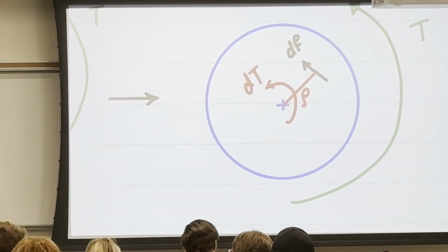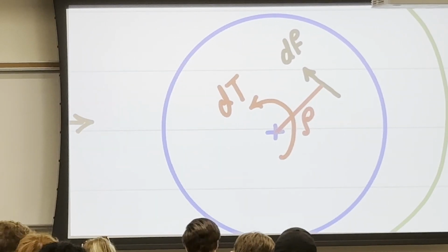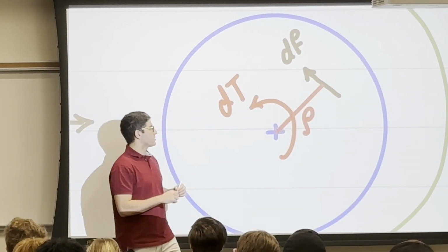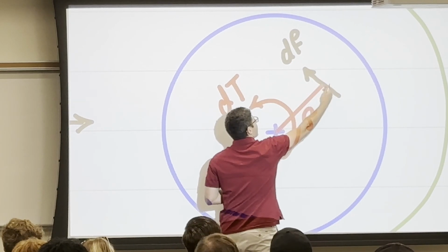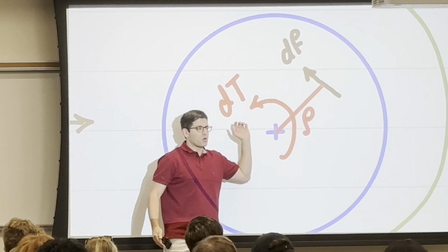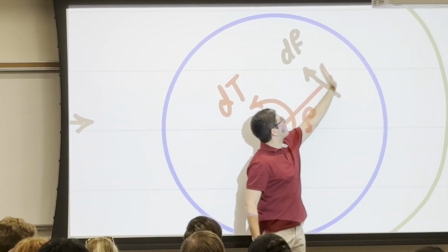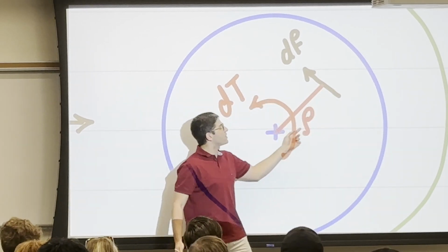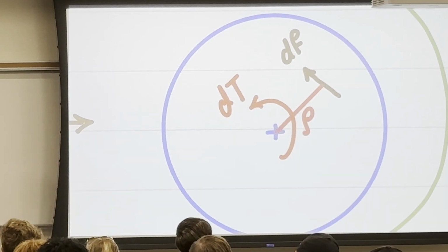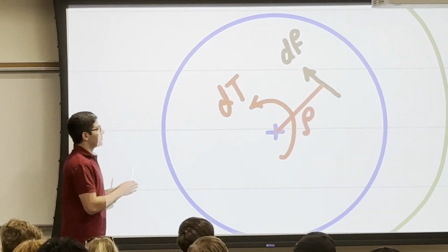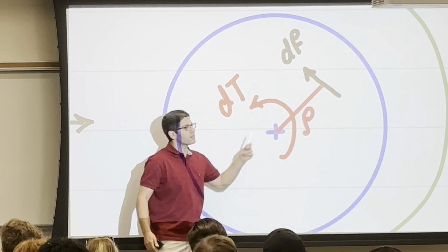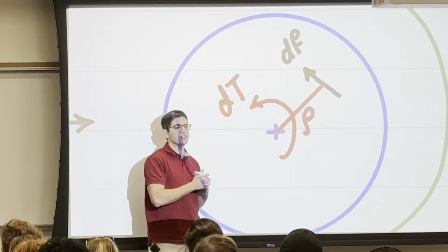So now let me explain something which might be obvious. This force, which I apply at this distance rho, gives me a torsion, right? So what if I took a force that's a little bit farther from here? So I'm increasing rho, right? When I increase rho, will this get me a higher torsion or a lower torsion? Higher. Which also tells you that the stresses further from the center are where I have the higher shear stresses.